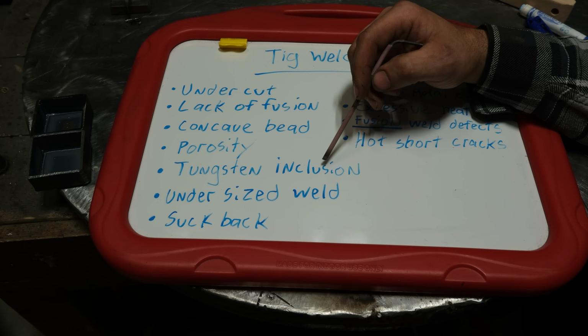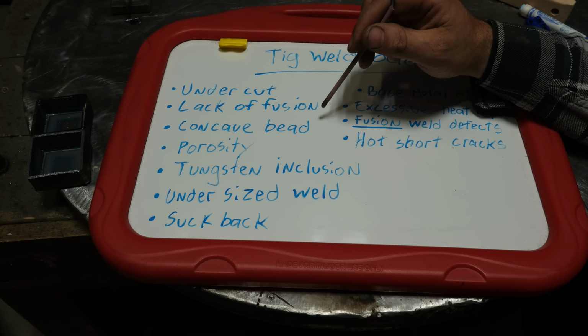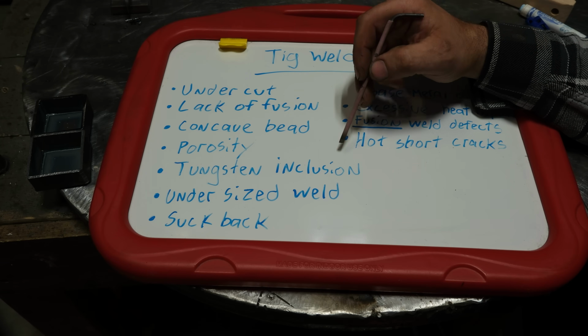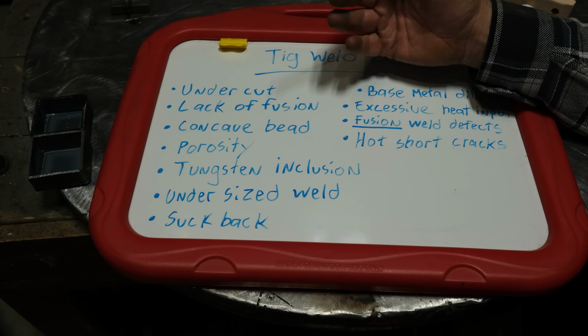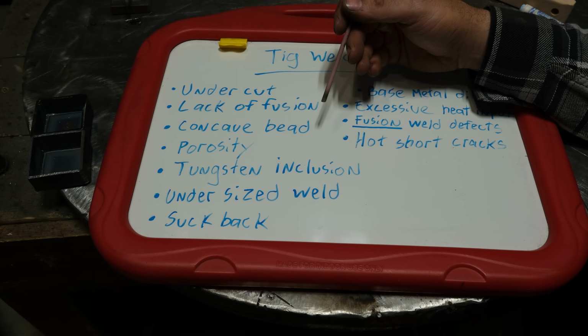Now, as far as the tungsten getting swiped in the molten material where it doesn't kill the arc, is that going to leave an inclusion? Possibly. So in the pipe welding world, which I'm now involved in, we typically use 1/8" tungstens.